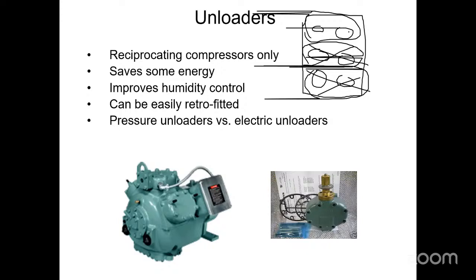So I can put 2 recip compressors in the machine, and I can put unloaders on 2 of these on 1 of the compressors. The other compressor doesn't need any unloaders. It can just sit there doing its own thing.